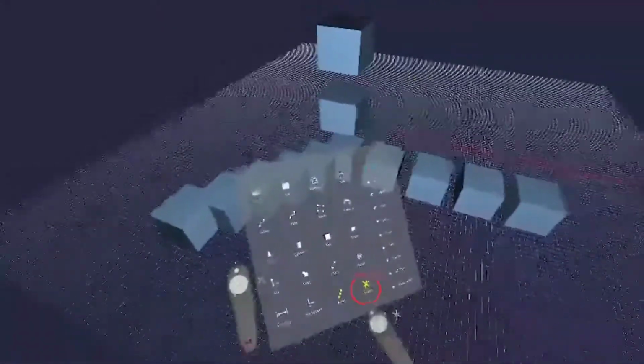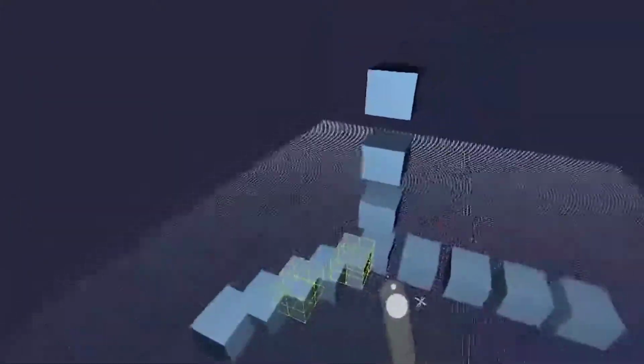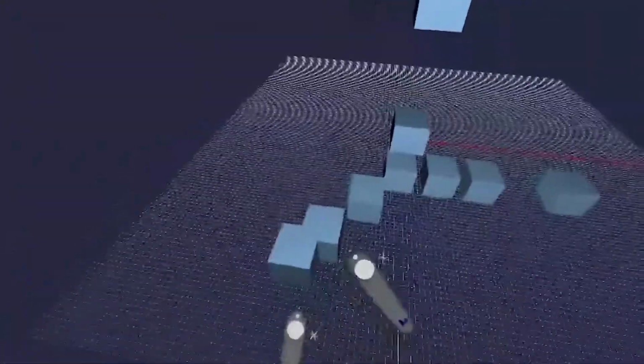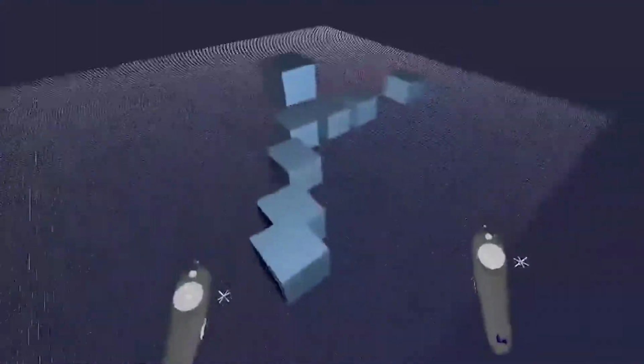So let's go ahead and delete a few of these just to show you how you can start to design with array but not be constricted to it. In fact, I want to change my C-plane to match the diagonals here, so instead of having the XY like this, I want to have the XY in this direction.